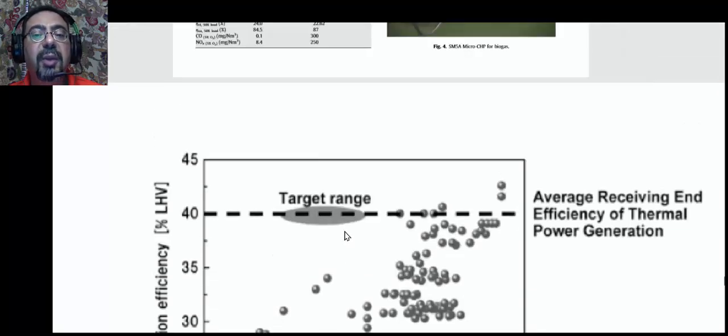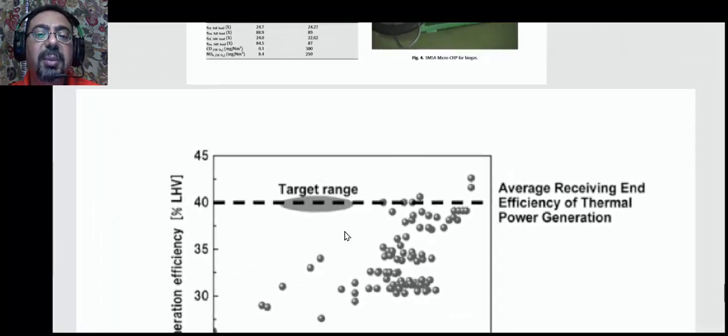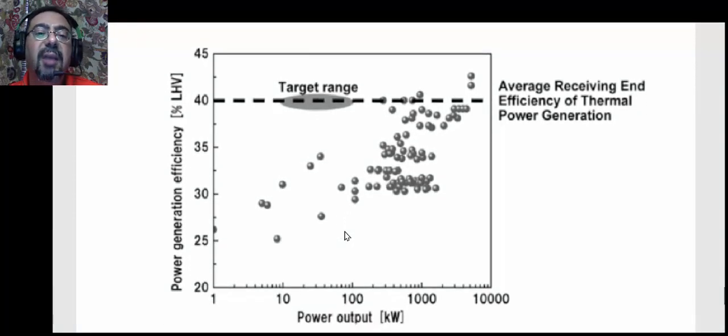Okay, so the Department of Energy was saying, well, this idea of combined heat and power cycle would be great if only we can match the efficiency of a steam power plant from those small units. Then it's double winning basically, right? Why double winning? Because you are using the Q. The steam power plant does not use the Q rejected. All the heat going into the condenser just goes wasted in the river. But if you do it in your house, you will be able to use that Q.